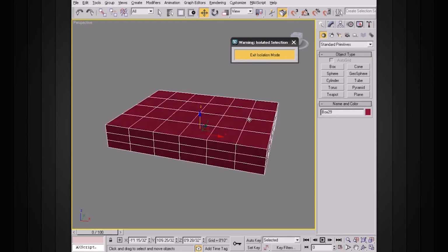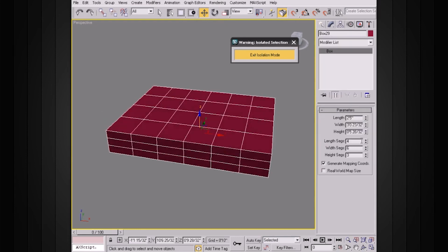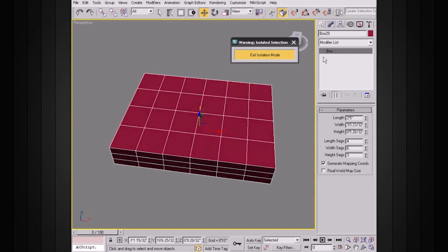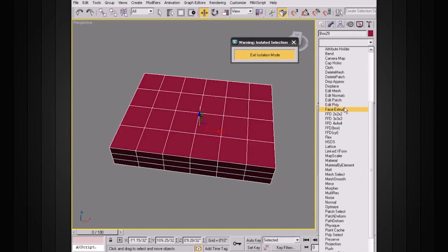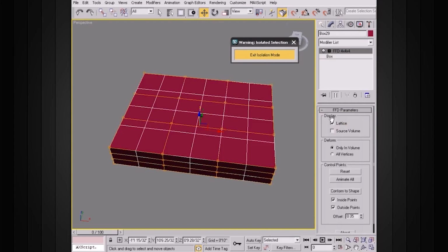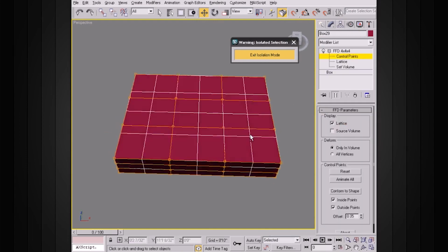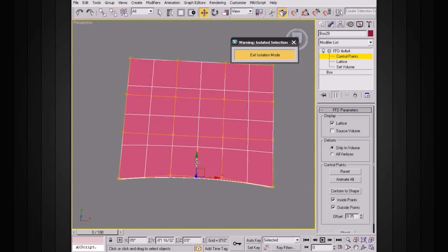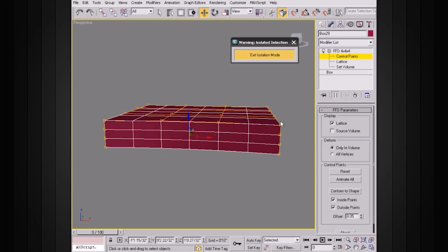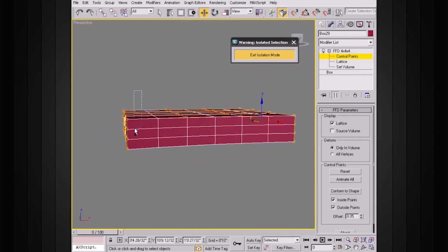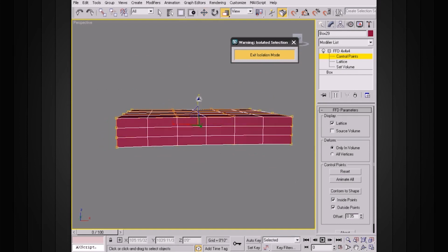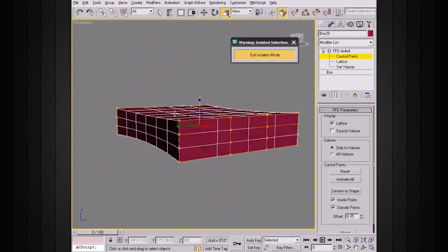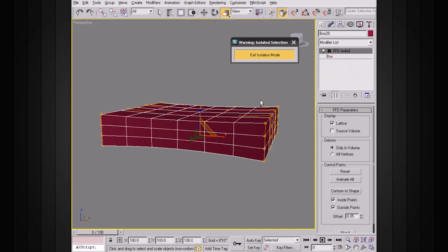Now let's shape this a little bit. The divisions I have are 4x6x3, so you want to have a little bit of resolution in here at this point. To deform this, I'm going to add a freeform deformer. Okay, and I'll go to the control points. Let's grab these on the side and pull these forward a bit. Okay, let's grab these and scale these up along the Z, to give it an interesting little shape there, until you get something along those lines.